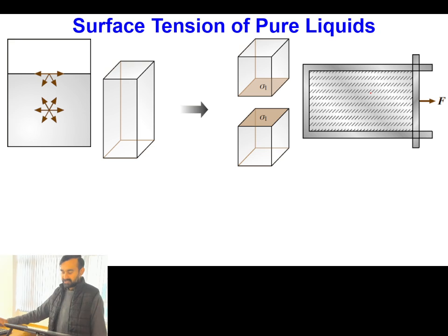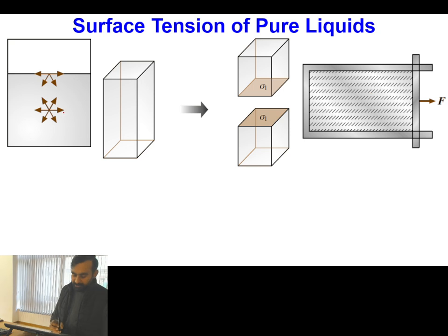If you look at the origin of surface tension, it comes from molecular behavior. If you have a molecule present in the bulk of the fluid medium, that molecule will have interaction forces, attraction forces, from the surrounding molecules, and as this molecule is surrounded by similar types of molecules, the nature of the interaction forces will also remain the same. Other than the nature of the surrounding molecules, it also depends on how closely or how sparsely the